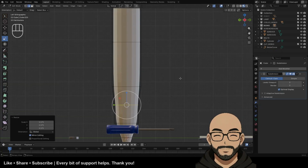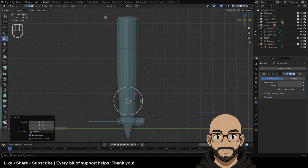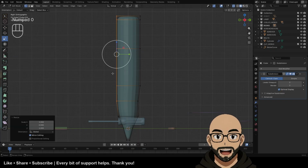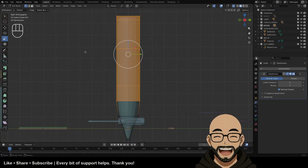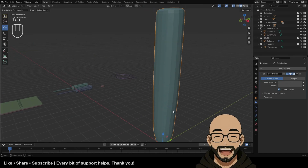Let's go into the side view, a bit easier. And let's change our mode to X-ray as well. And of course we don't want this all to be different. So I'm going to select all these vertices. If I hit scale and hit 0 on the numpad, I can line this all up. 0, boom. And then I can fill these all in together. We kind of have a pencil.